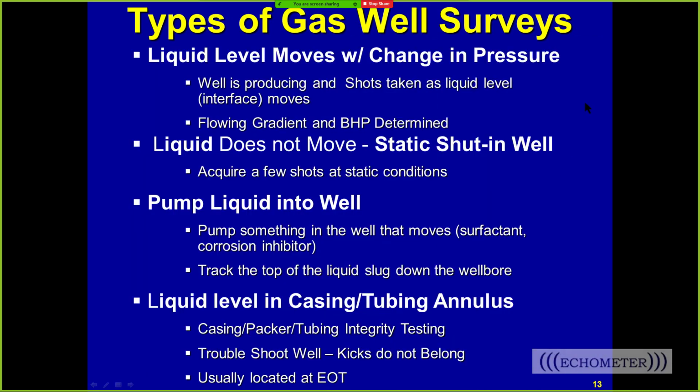So there are different kinds of liquid level surveys you can do on gas wells. You can have the liquid level that will move with change in pressure. That's one type of test you might do. Maybe the liquid level doesn't move, and that would typically be a well that might be shut in, or maybe there's a standing valve in the tubing that traps the liquid. Or you could pump something into the tubing, and you may want to track it as it falls.